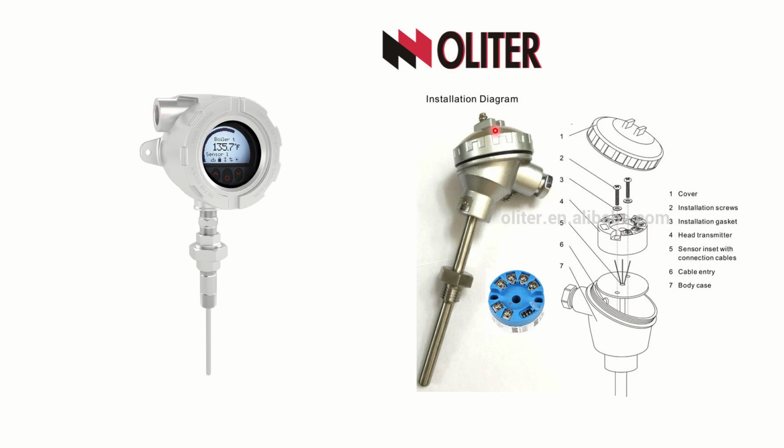Now you can see here, this is a protective sheath. I have shown an exploded figure here. This is the cover. This is actually the plate through which the terminals of the sensors are coming out. If you do not apply a head mounted transmitter here, then you can have these terminals screwed.